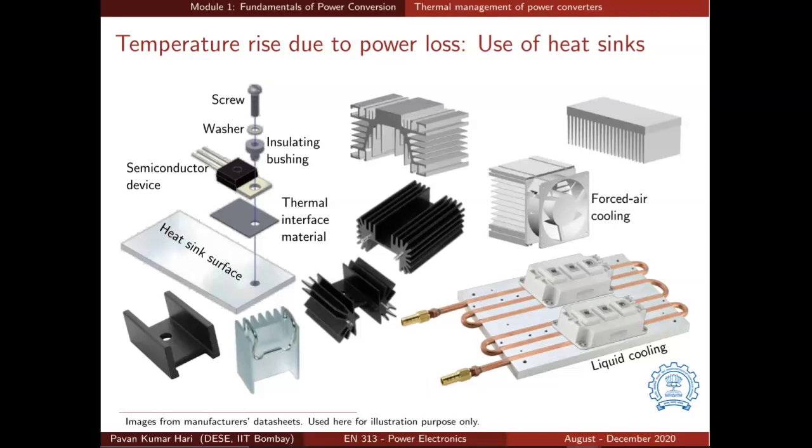But the heatsinks need to be selected based on the power dissipated in a switch, the thermal conductivity of various elements in the heat transfer path and the safe operating temperature specified. Let us try to take a closer look at the heat transfer mechanism to arrive at a simple thermal model which is widely used for the design of heat sinks in power electronic converters.